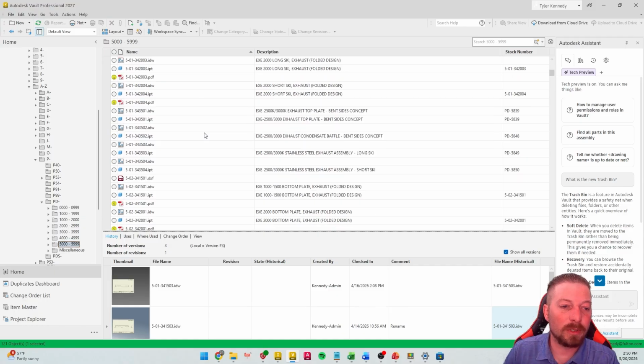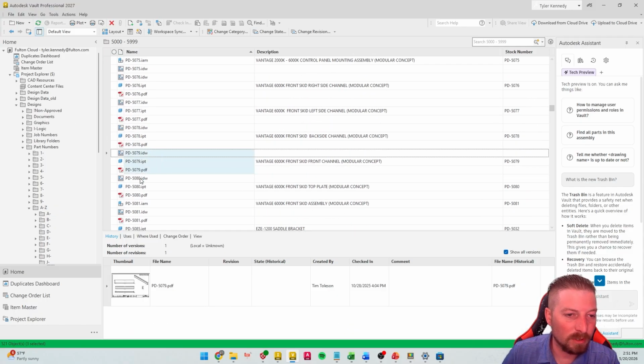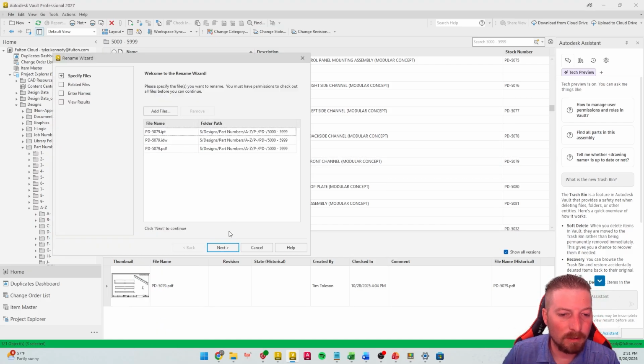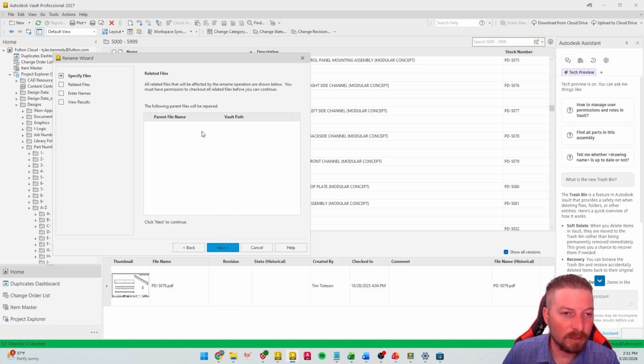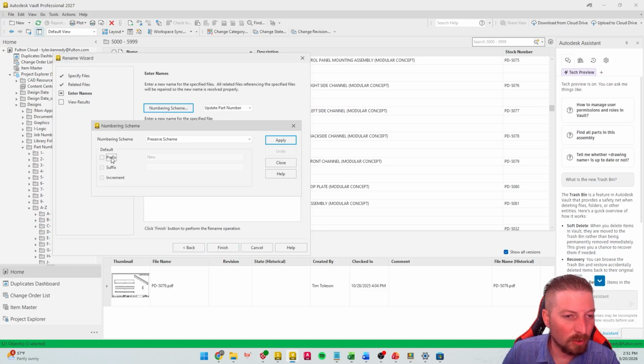So how do you do that? It's really simple. Let's say I was here. Let's go, yeah, we'll just do this. I'm going to grab all these 5079s, right click, and choose rename. I don't need to add any more files. I click next. Little tricky here. I have to go to numbering scheme, turn off prefix, and turn it to none. We're not using any numbering scheme to pull this.